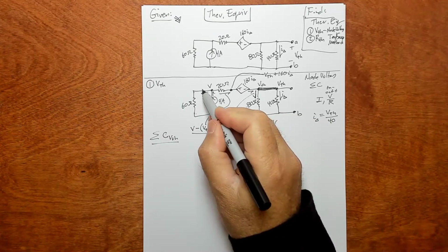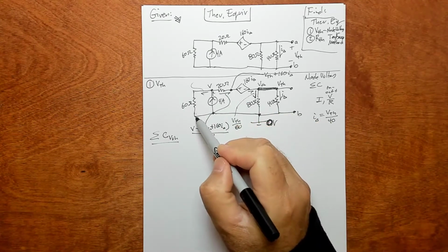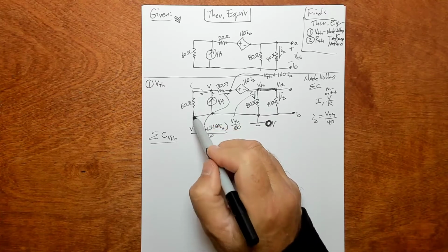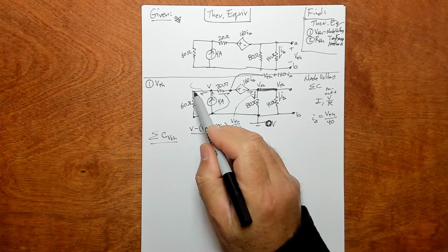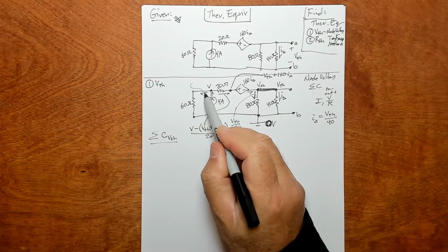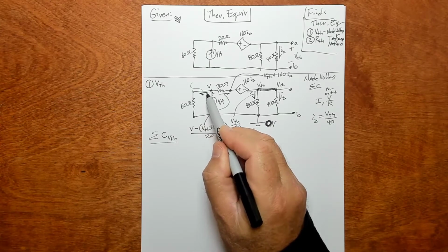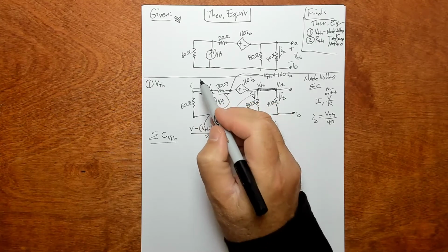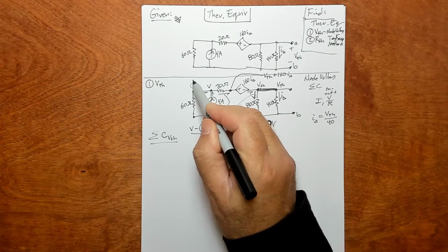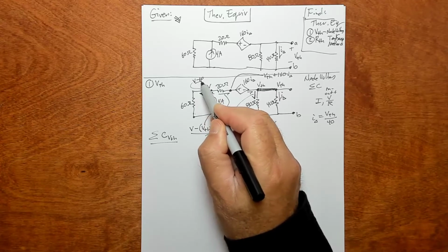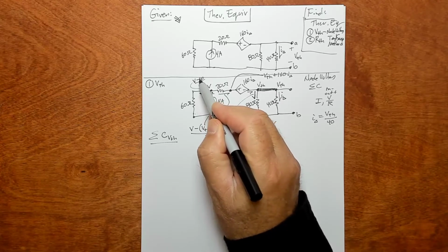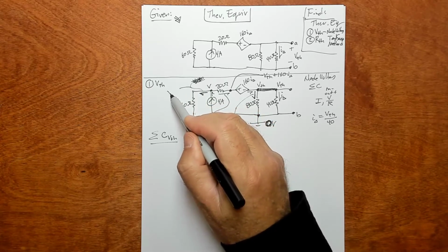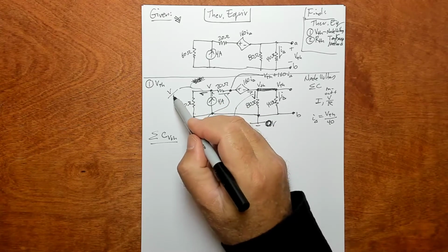And then this guy right here, it's 0 volts on the bottom and V volts at the top across this resistor here, right? The current through here is the same as the current right here. This current goes down through here, and the potential difference across this guy is just V. This guy here is V over 60.